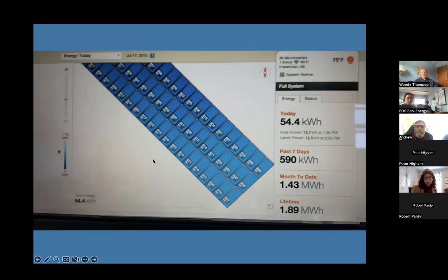Because they were microinverters, the microinverters upload all of the data that they collect about the output power from the solar module. They upload it onto the web where it is recorded and it is accessible by the homeowner and by the installer. Here we see each individual solar module. This one gave 897 watt hours. This one gave 907 watt hours so far that day. It also gives you the historical yield, the lifetime of the system, and how much energy it yielded that month. As you can see, the lifetime of the system is about the same as the month, not a whole lot of difference there. The system was very newly installed when I took this screenshot.